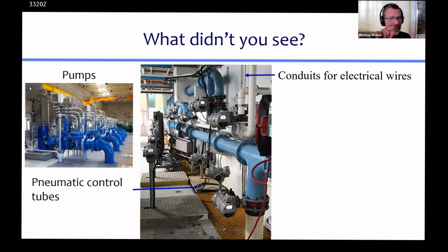And then the air goes in a hose, in a tube, up to the actual valve that you want to control, and that air pushes that valve closed or open, whichever way you're going. Okay, so you have software that controls electricity, that controls a little valve, that controls air, that controls a big valve.